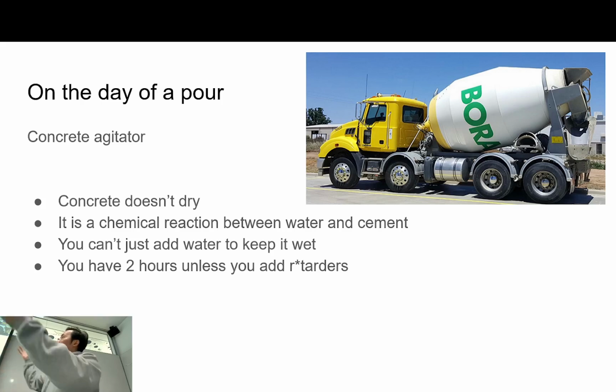Once that's all mixed to proportion in the truck, it starts a chemical reaction. So concrete doesn't dry per se, concrete cures. Which means that if you put water into a concrete mix, you can't just keep adding water to keep it going and keep it wet. It will solidify at some stage. It's a chemical reaction between water and cement, and you basically have about 2 hours once the water touches the cement, unless you add retarders into the concrete mix,